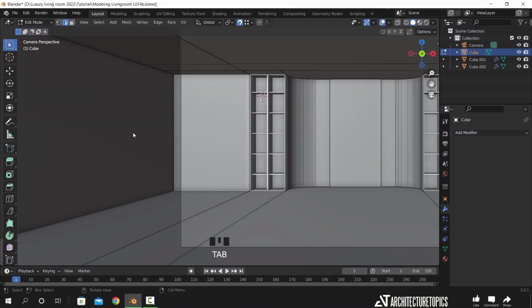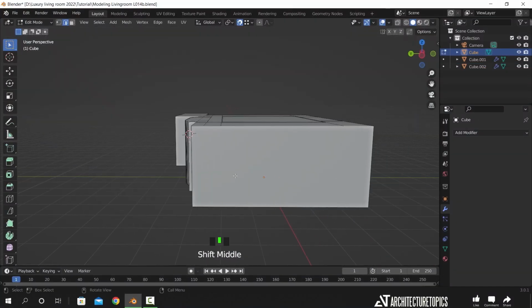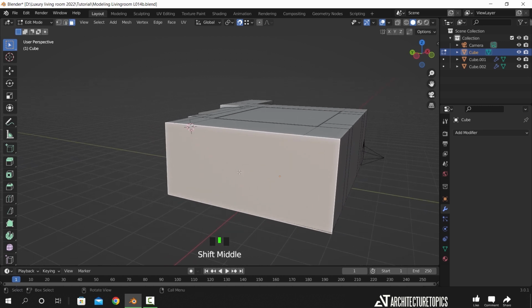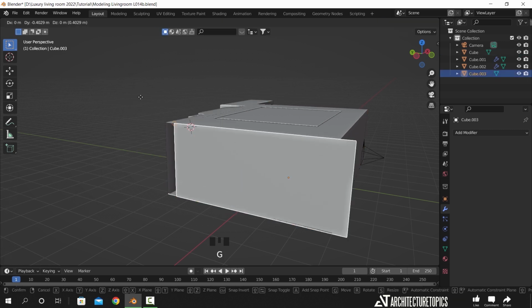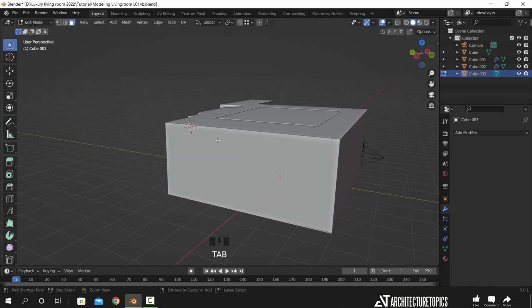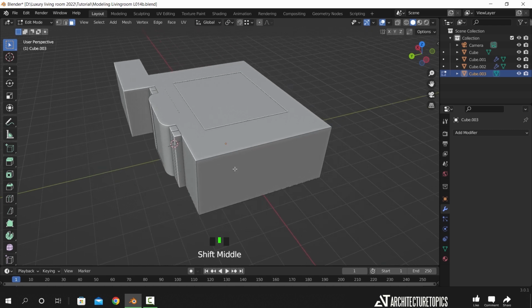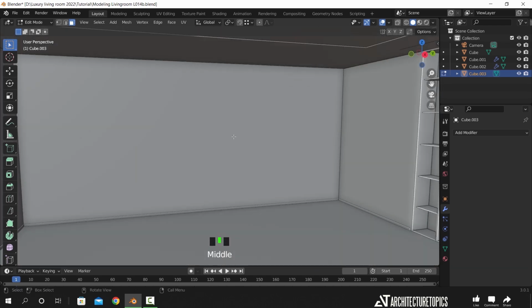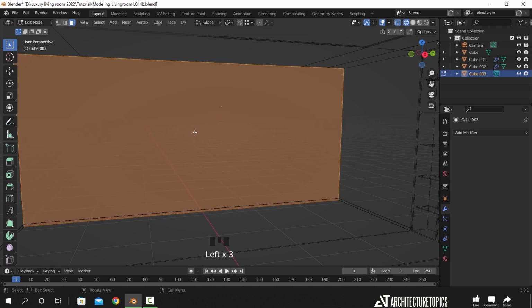For the lighting part, we will start with the natural light, and for that, I need to cut a hole in the left wall to work as a window. I won't be adding one since it's outside the camera frame, so we just need an empty area for the light to come through. The left wall is the same as the ceiling, and though we can delete it and add a new plane, I will work it around in edit mode since, as we said, it won't appear in render.